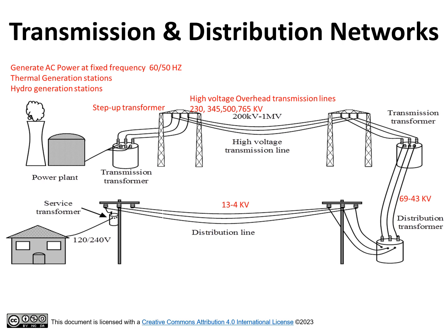Industrial customers and big facilities are usually directly connected to this voltage level and have their own service transformers to reduce the voltage. For a residential customer, service transformers are used to reduce the voltage to 120 volt level.